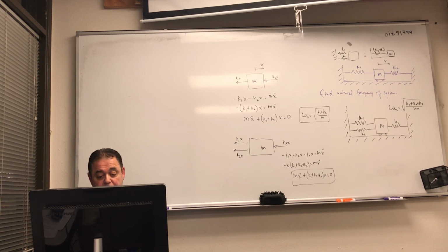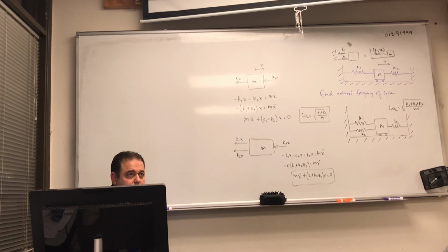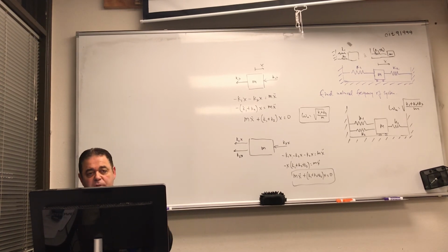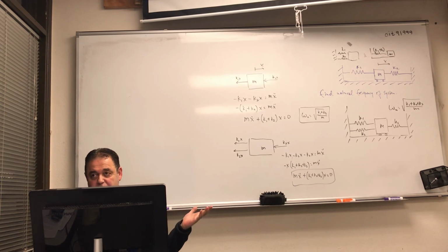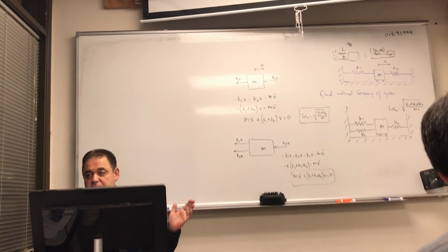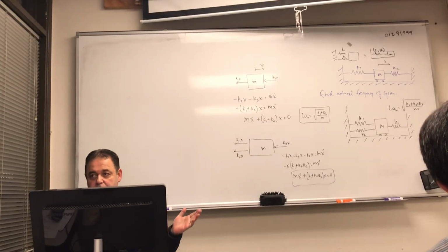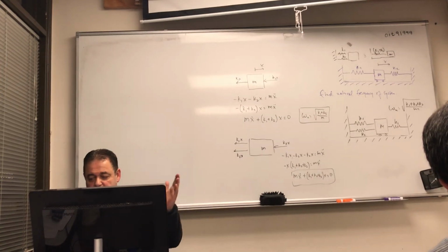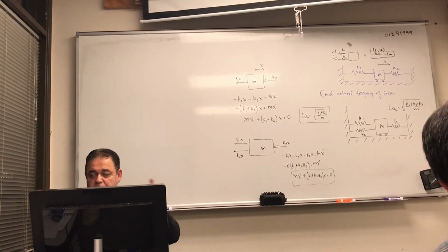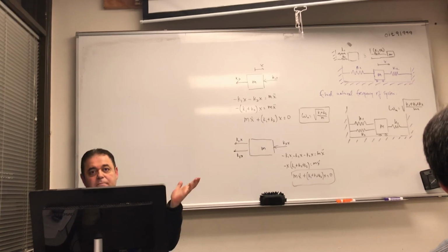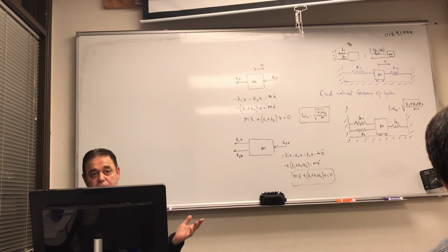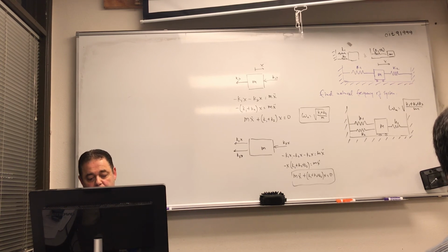But one thing you may probably be asked to do is to get, for example, an equation of motion, because that's really all we did in the first chapter, by using the energy method. What does it mean? Well, it means you express the kinetic energy, express the potential energy, sum them up, and then just take the derivative of that, and whatever equation you get is the equation of motion. Okay?